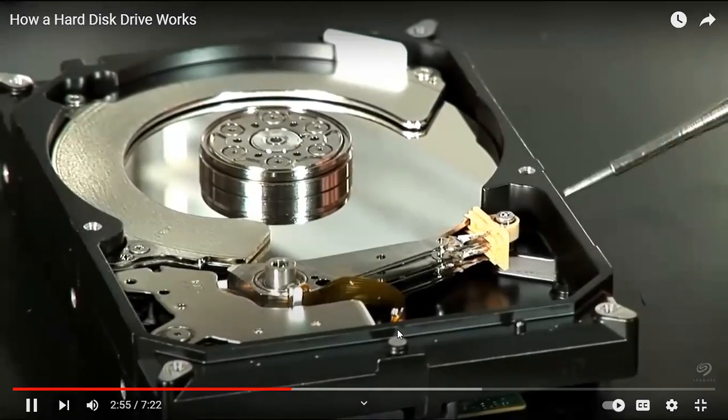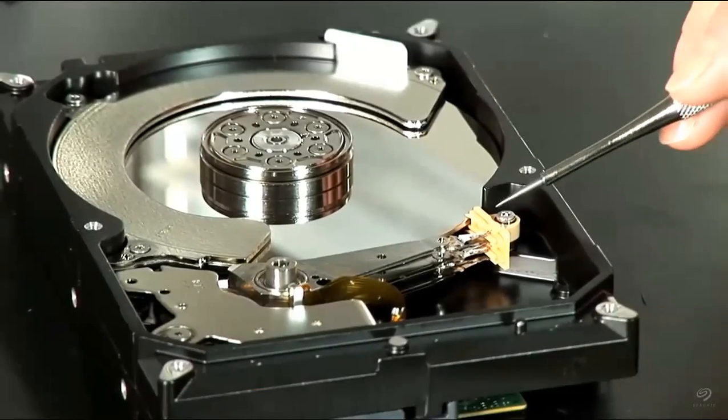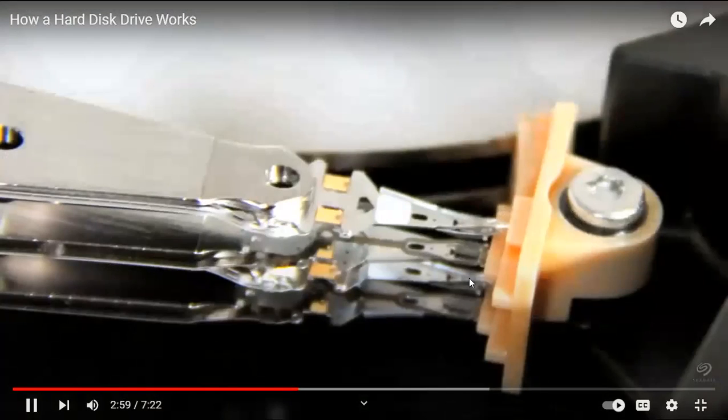When the drive is powered off, the heads are resting on this ramp. The arm swings off so that the head. So what happens when you turn off your computer is that the head comes to this ramp and is stored inside this ramp, right? When you power on your computer, the actuator arm again goes towards the hard disk, right? So when you turn it off, it is here. The heads are preserved and they're not touching the media or anything.